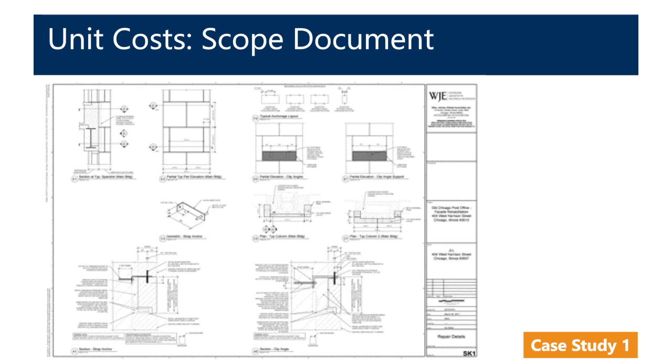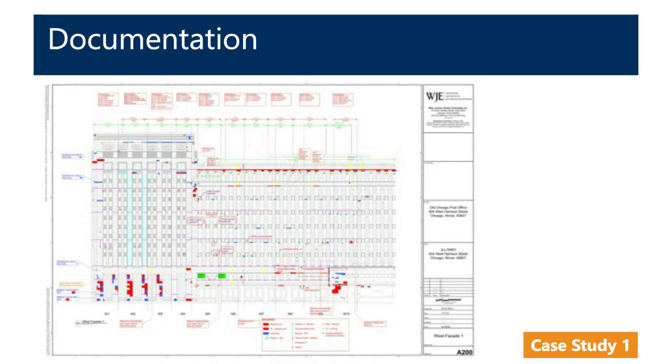So the contractor could actually give a unit cost to replace limestone, and it didn't matter on the size of the unit. We got a unit cost for a cubic foot, which included anchors. So if the size varied, it didn't matter. It was the same number of anchors, but quantity could be based upon an actual size of a unit. And you didn't have 20, 30 different line items for various modifications of the limestone. So it helped with getting an actual cost together at the end and throughout the project, it simplified it.